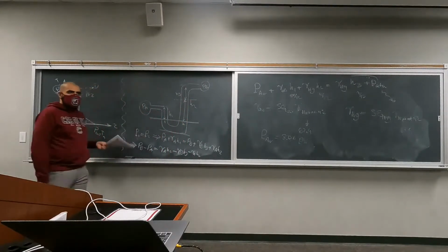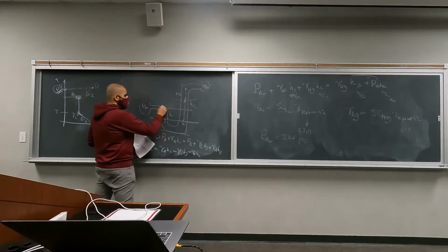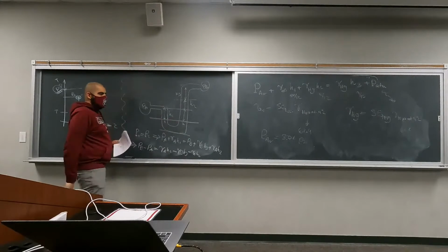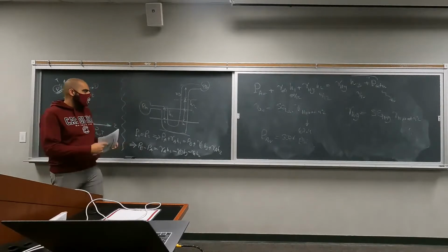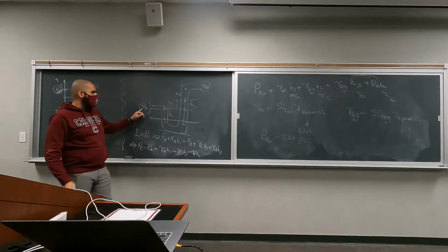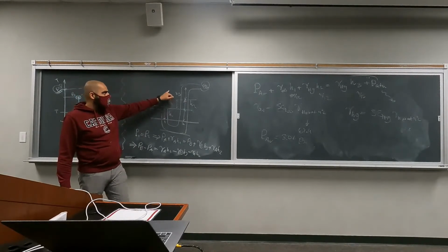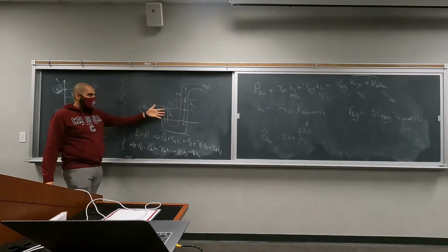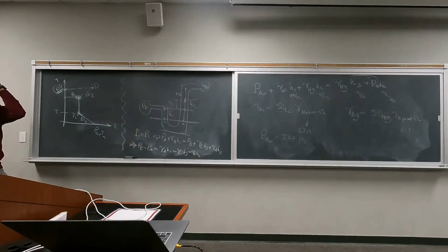We could actually make things easier here if we just took these 2 points. The pressure at this point has to be the same, right? These are made from the same liquid, they have the same height. So essentially, we could have said, let's call this new one H4. We could have said PA is equal to gamma A H4, minus gamma B H3, plus PB. Right? It's the same idea, we're just removing some unnecessary calculations from it. Is this clear? Yes?